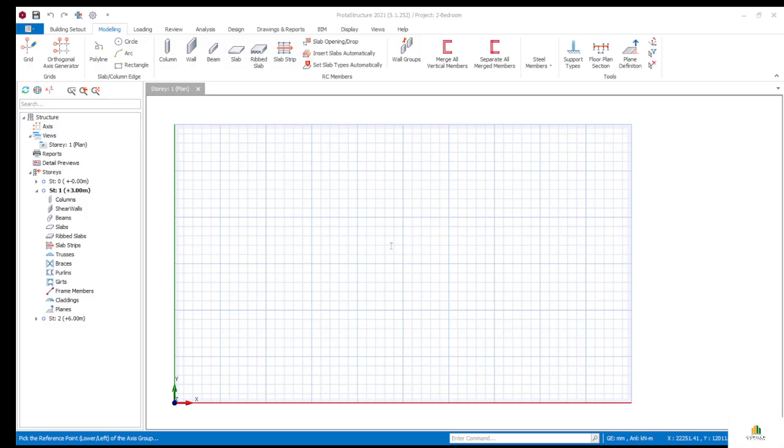So let's say you have your architectural drawing, you've done your general arrangement to know where your columns should be. You know the measurement between two columns. So there are axes at those columns, and the space between them is what you place here. So the moment you see axis spacing, or in brackets spaces, 5,000 asterisk 3, the asterisk there is multiplication, right?